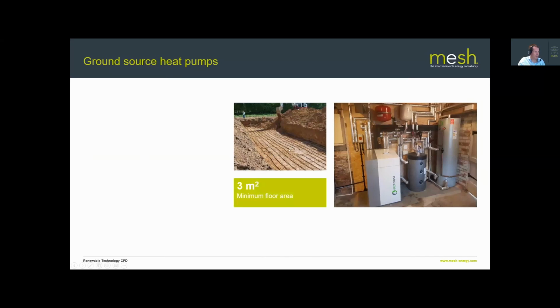Externally, depending on the type of collector system you use, you may need a fair amount of land outside. If you haven't got that land, it doesn't mean you necessarily can't use a ground source heat pump, but you might need to look at boreholes rather than flat loops, and that's a bit more expensive.